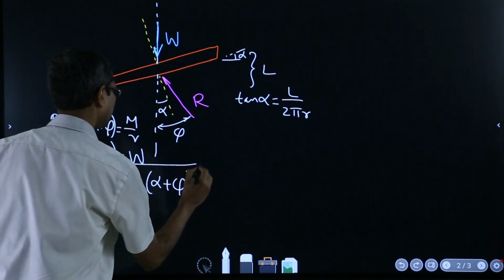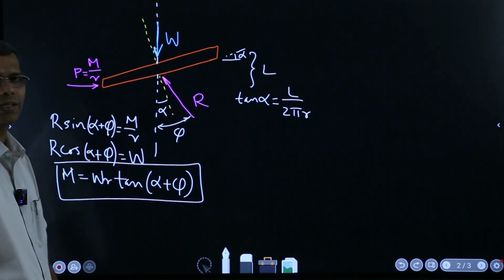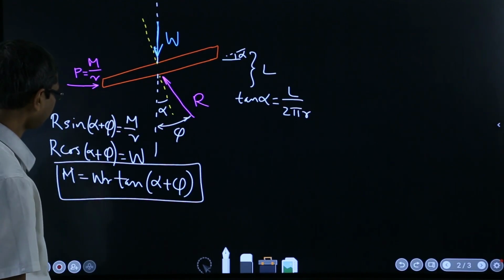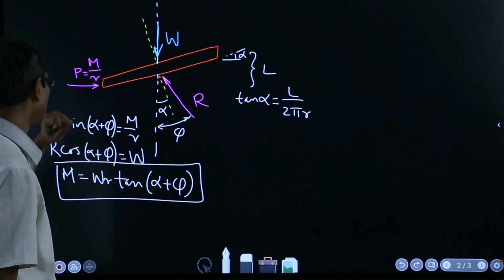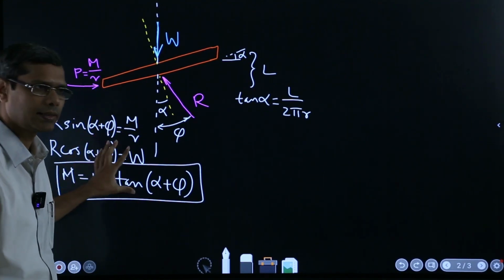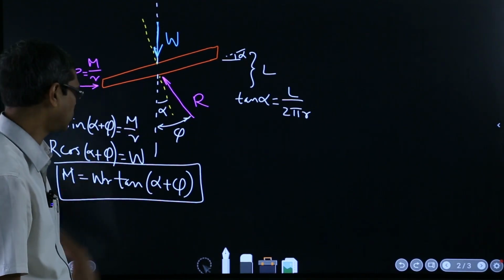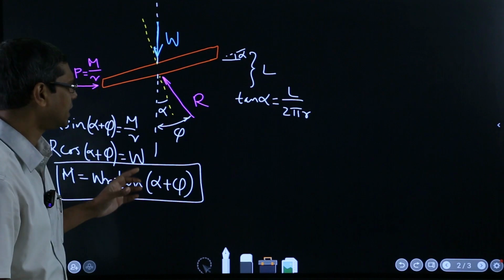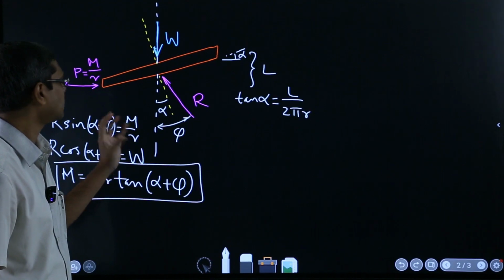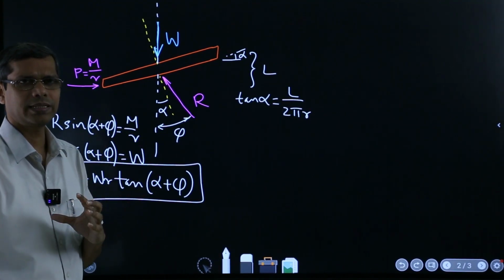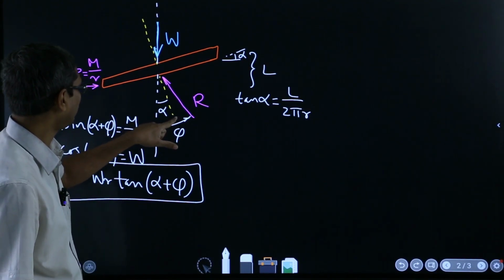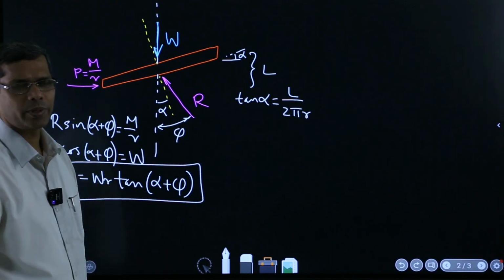Right. So this is another way, whatever is comfortable to you, you think in those terms. In fact, I would suggest that you should be comfortable with both the viewpoints. Okay. Now, this is the way to look at this situation. So the advantage I'm just going to tell is that you can now very easily think about it. Suppose the screw thread is self locked, in this case the locking condition will come from the fact that alpha will be equal to phi.